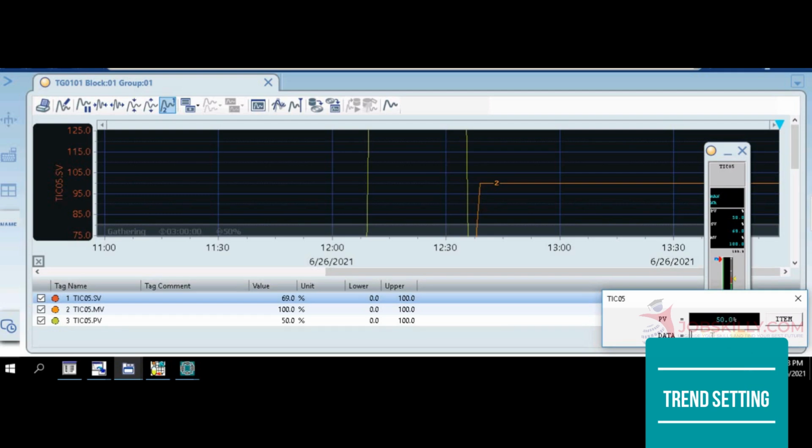If you want to check in real time, you can put it in calibration mode, then only you will be able to check this. Otherwise, you can check it in running operation. It will take the process value and hamper your process. So when you are checking, we will go for calibration only. Here we are taking the value because we are working on a simulator.